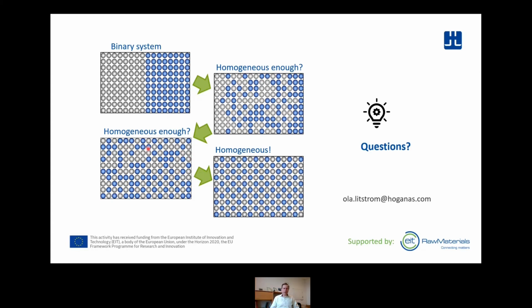If we mix a little bit more, it looks like this. We cannot easily see that we have a concentration of copper or iron to the left or right or top or bottom. So this is probably homogeneous enough. This will be good enough to make consistent sintered components.